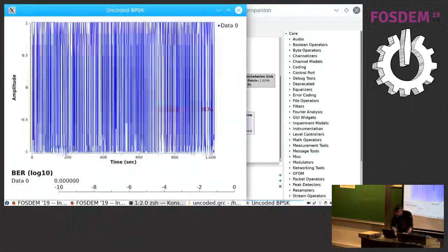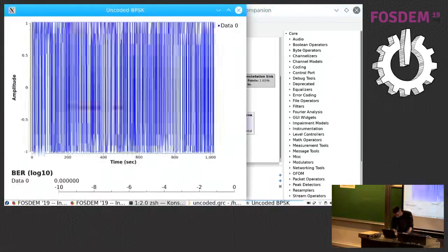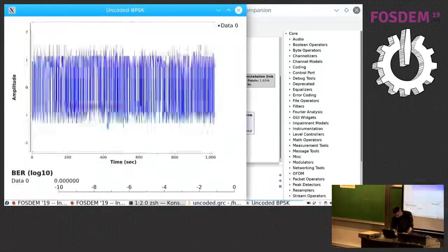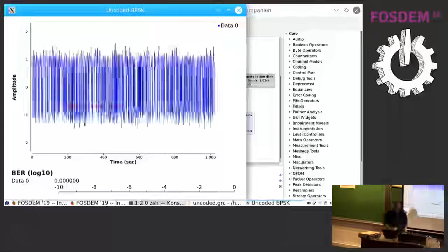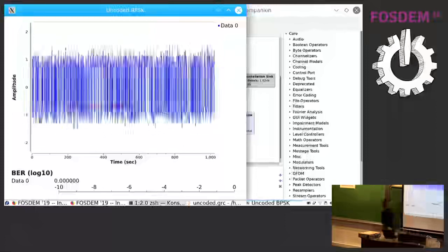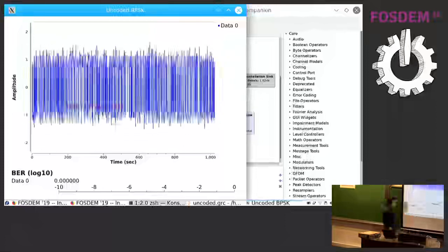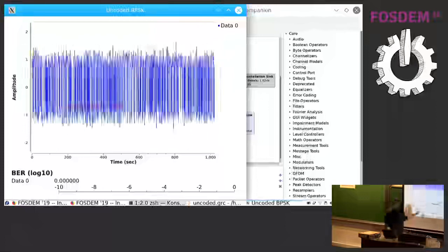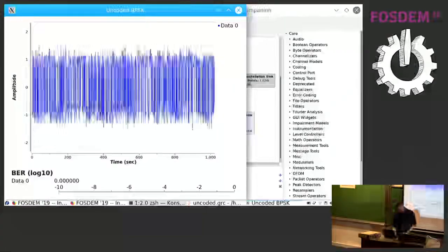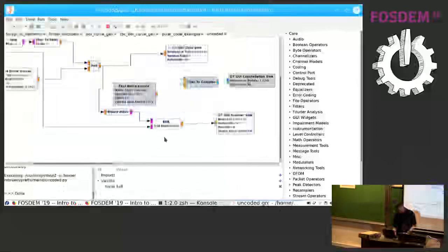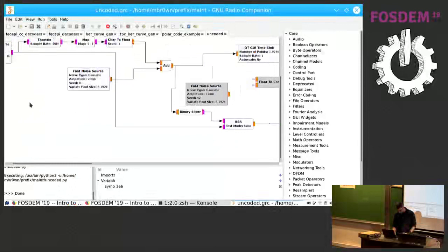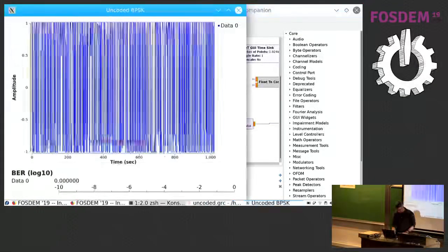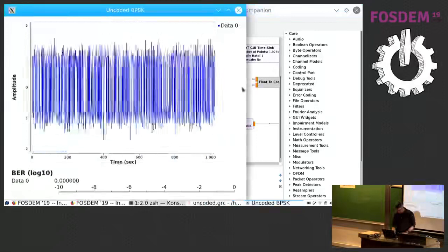And what you care about, which for some reason is failing me right now, is the bit error rate is actually 0, and that's not supposed to happen. So this number should be higher than that. It should be about 10 to the -6 or -4 or something like that. This is what I get for doing demos. Oh, I was playing around with the amplitude. Yeah, I'm just going to crank it up for now. Where's my slider?